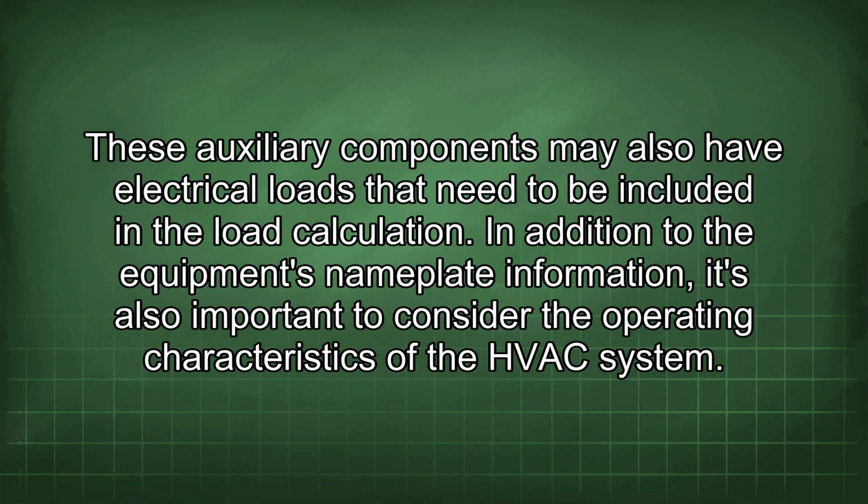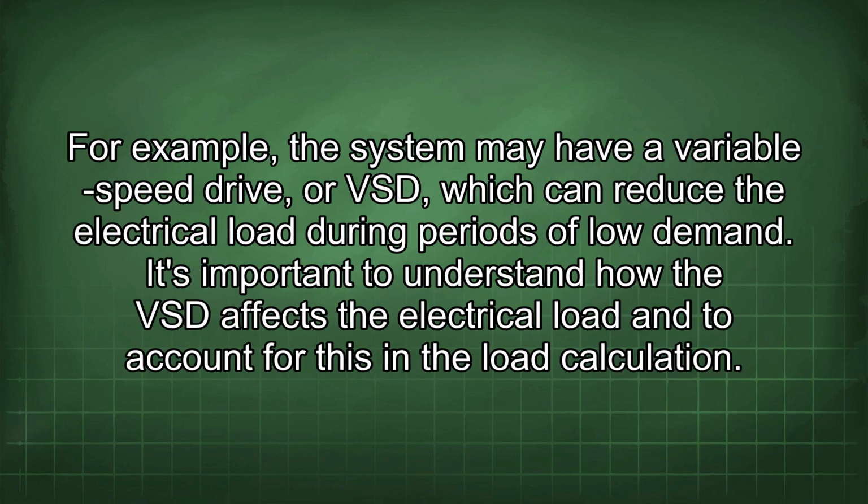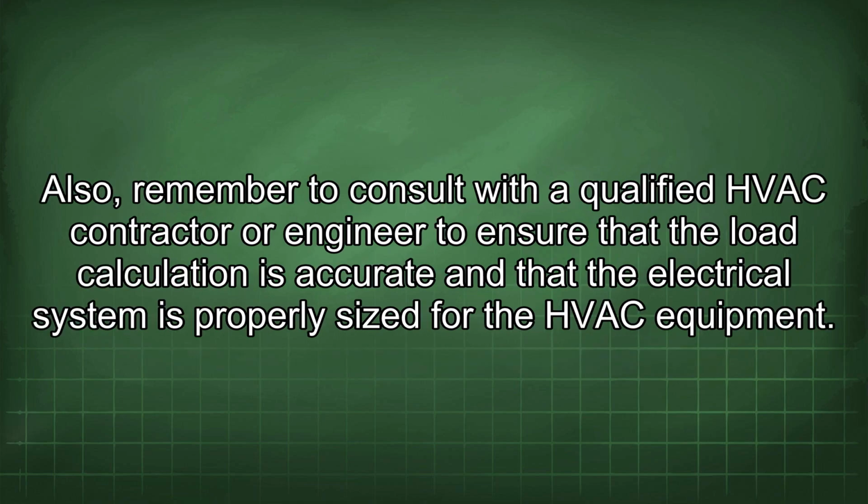In addition to the equipment's nameplate information, it's also important to consider the operating characteristics of the HVAC system. For example, the system may have a variable speed drive, or VSD, which can reduce the electrical load during periods of low demand. It's important to understand how the VSD affects the electrical load and to account for this in the load calculation. Also, remember to consult with a qualified HVAC contractor or engineer to ensure that the load calculation is accurate and that the electrical system is properly sized for the HVAC equipment.